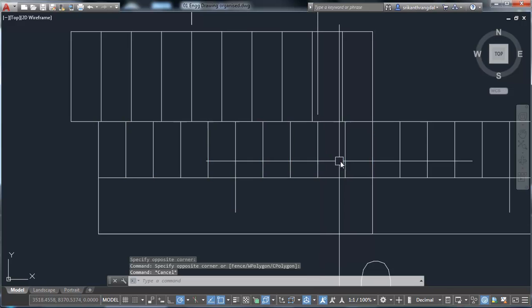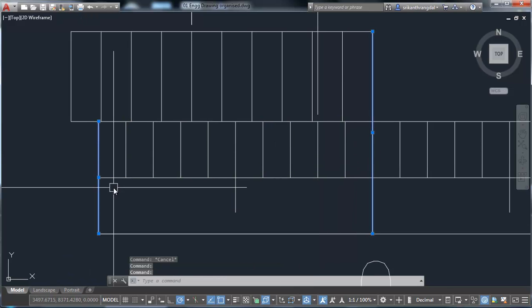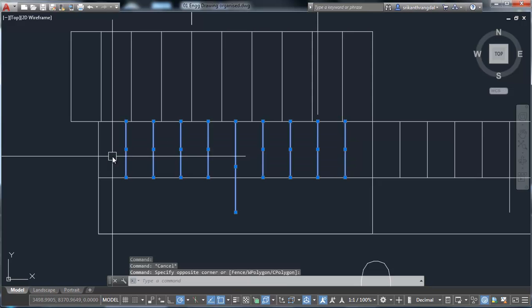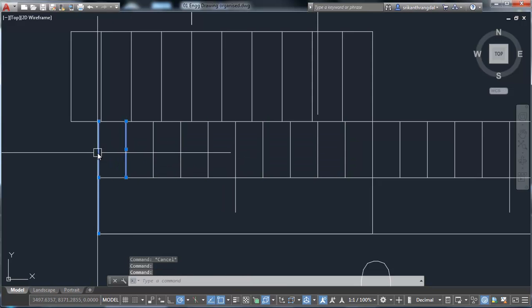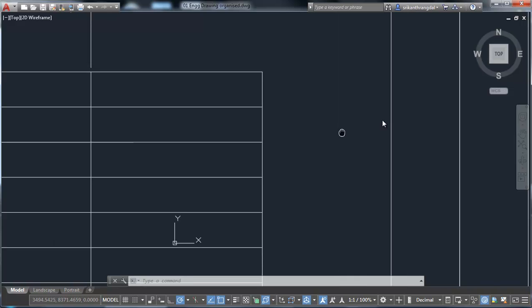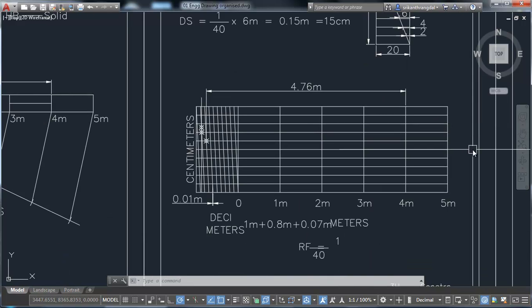The distance between these two lines is exactly 1 meter, which is divided into 10 parts, which means the distance between each of these subdivisions is 0.1 meters. The challenge in measuring more precisely is that you want measurements which are 1/10 of 0.1 meters, and that is very easy to do with the diagonal scale.